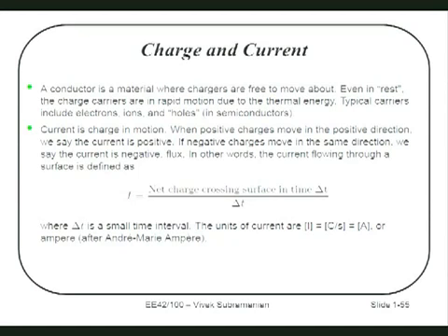So we've now seen the difference between capital I and small I. Small I, in particular, when we define it with respect to a particular variable such as time, tells us how current is changing and what its value is at a particular time. Capital I represents the net charge crossing a surface in some interval divided by that interval, and that will typically be assumed to be non-varying if it's a capital I.